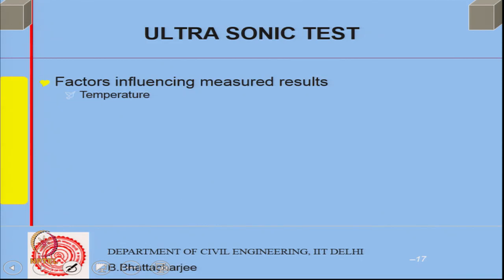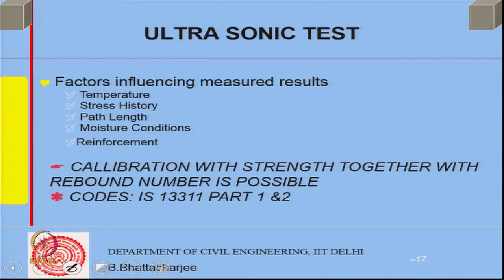So, what are the factors which influence the results? Temperature, some stress history sometimes, path length, obviously, but important is moisture condition. If there is moisture, you will get different results. If there is reinforcement present, it will modify your result, because velocity in steel is much higher.